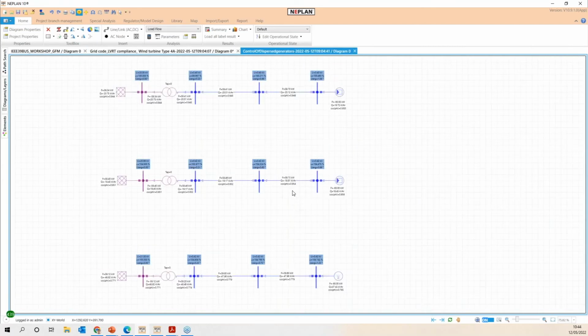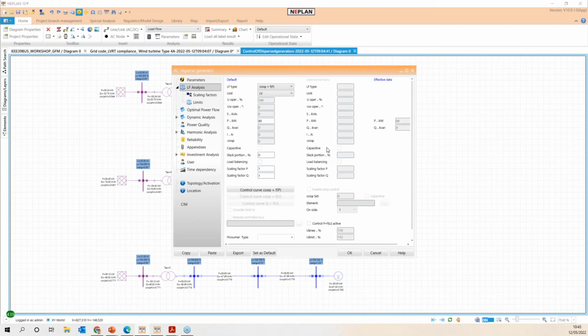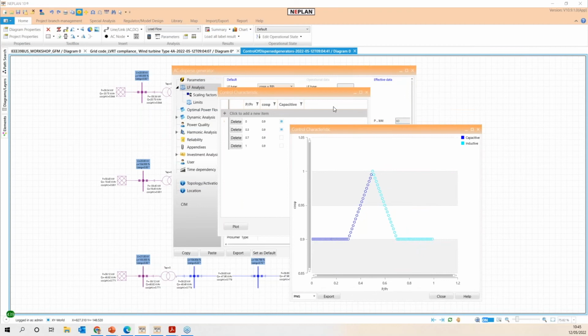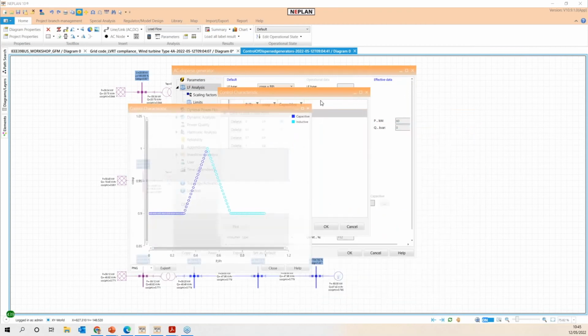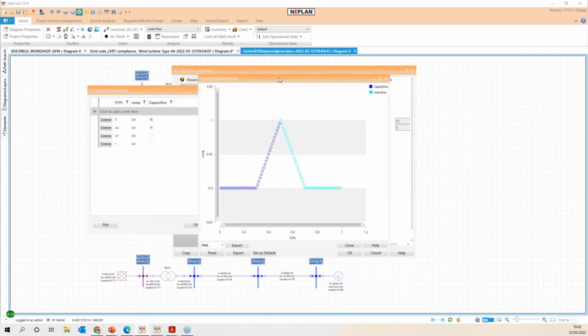Finally, let's talk about the control modes available to support the active and reactive power controls. The active and reactive power controls can be performed on the specification of the model for distributed generators. And we can see the different specifications from different control curves, depending on the specification of active or reactive power support. We can define the curves here. And we can see how we can create, for example, control systems where we have the power factor as a function of the active power.